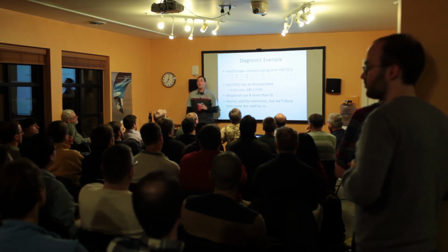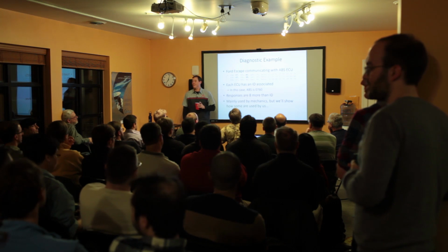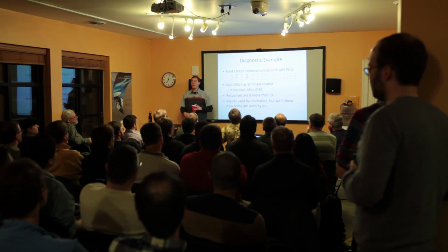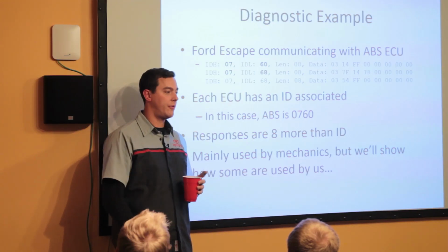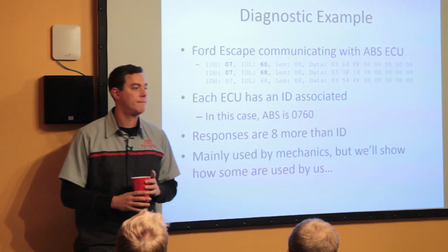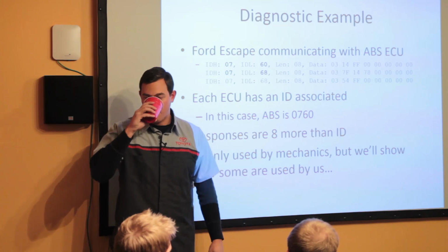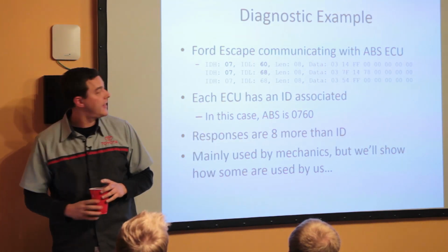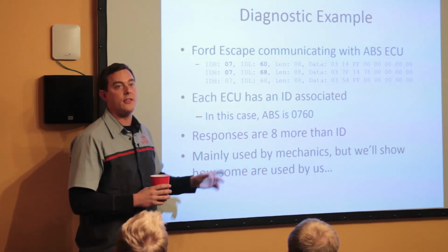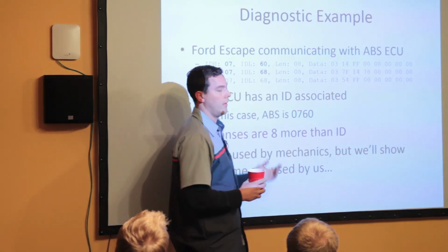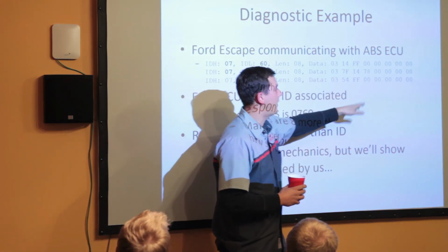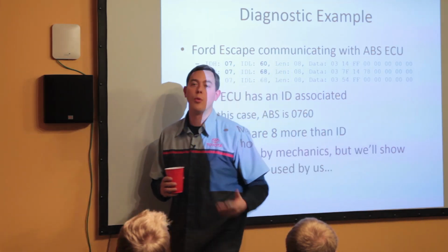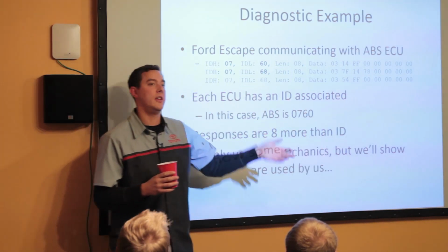Is there an assigned number authority somewhere? No, it's just however they want to do it. Each manufacturer is different. I think there's a list of standards for engines and for emissions and things like that. OBD stuff is mandated. But even though the OBD stuff is standard, I'll talk about ISO later. The first 3 bytes are standardized, and then the other ones can be proprietary. So Fords are going to be different than Toyotas, which are going to be different than GMs and so on.